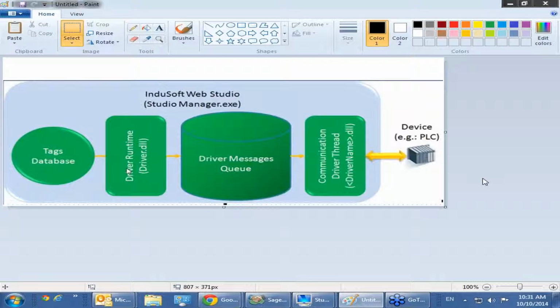Basically, the ZigBee host, like a ZT2550, and the ZigBee slave converter are set up with a software utility. You set it up on your computer, where you configure your COM port, and then you configure the RF channel, the PAN ID, and then the node ID. After that, you test the communication, and then in your application, it's kind of just like a COM port. Is that right, Robert? I tend to think of it more like a wire, but yes, you open it as a COM port connection, and you can communicate to your other devices at the other end.